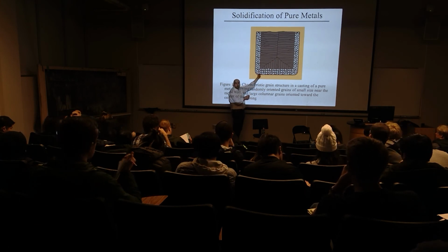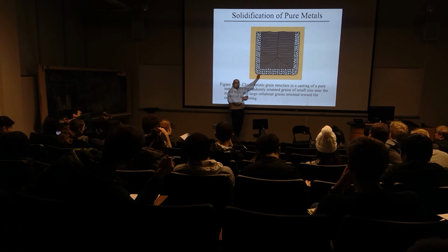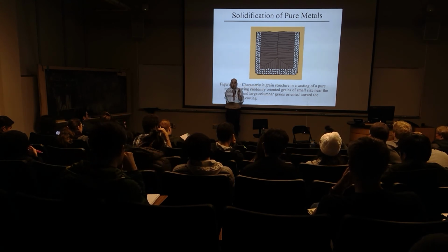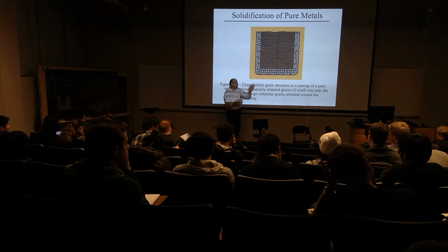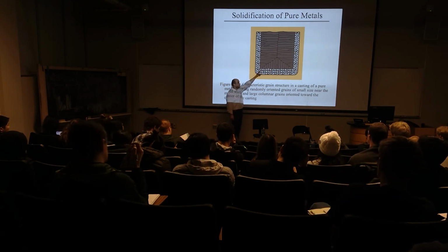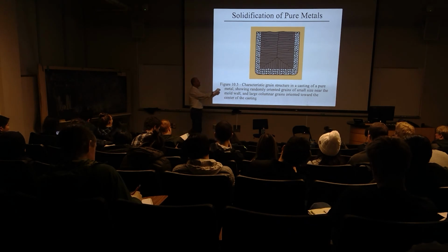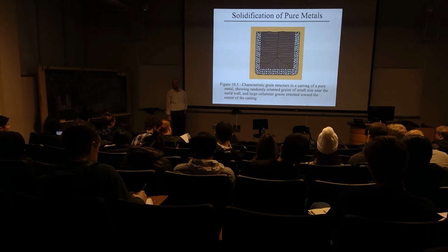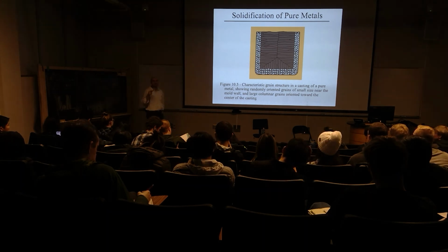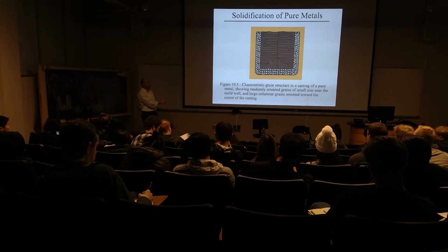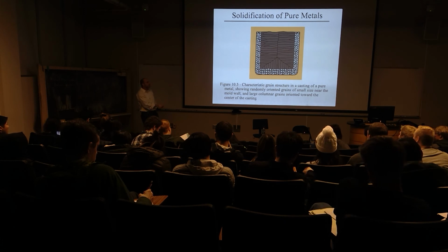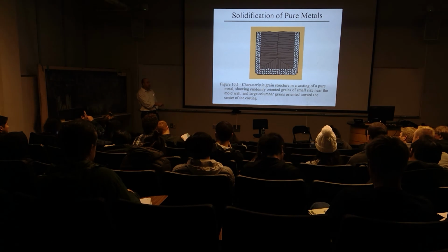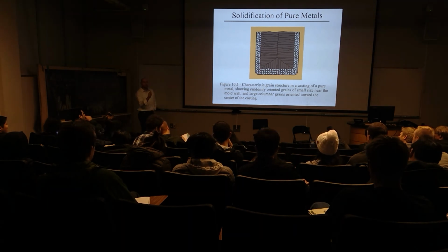So how do we make a casting as strong as possible? We make all this go to the entire thickness. That means we use thin parts, so we try to control this solidification process. Or we minimize the amount of heating up of the mold, and we try to extend that area as far into the interior as we can. So when you change the casting conditions, that might be part geometry, or the temperatures associated with pouring, that will influence how fast heat is taken away, and that will influence grain structure. That's you, right?